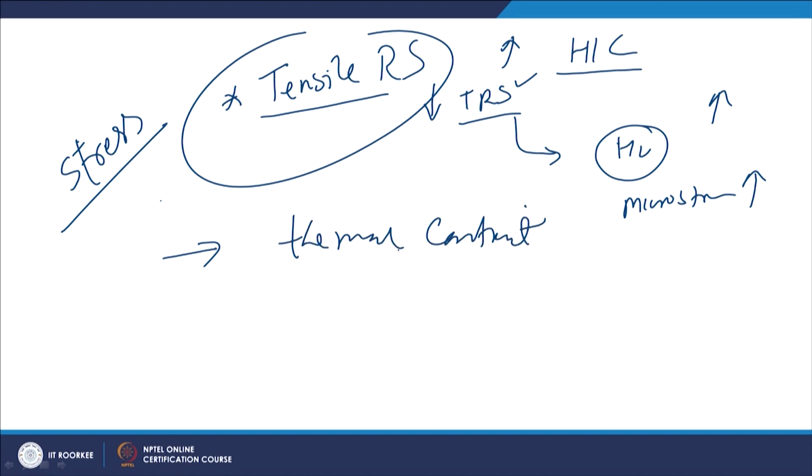This is the main source of the residual stress development, because localized heating of the plates during the welding causes the localized expansion, and subsequently on cooling the contraction is facilitated, but the contraction is not complete. So, left out strain due to the reduced thermal contraction leads to the locked in strain, and that in turn leads to the development of the tensile or the residual stresses.